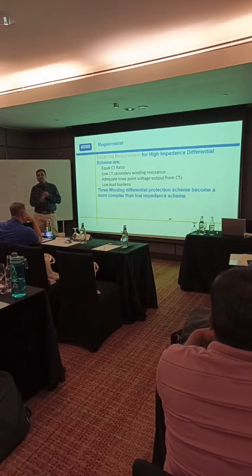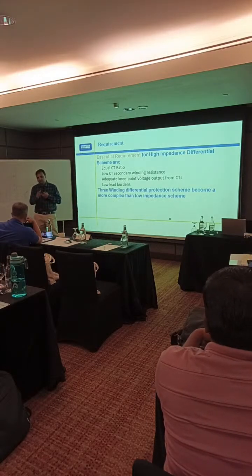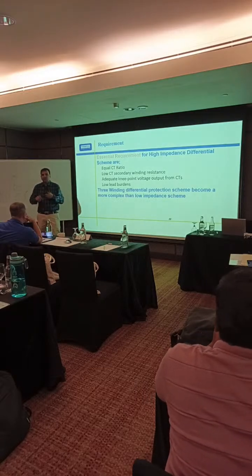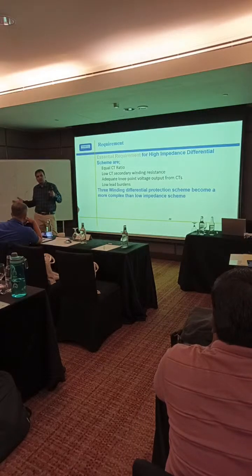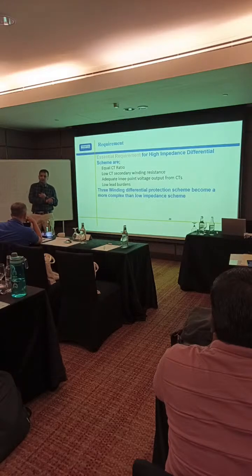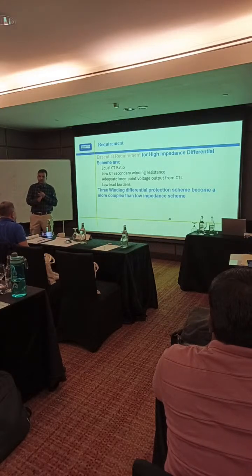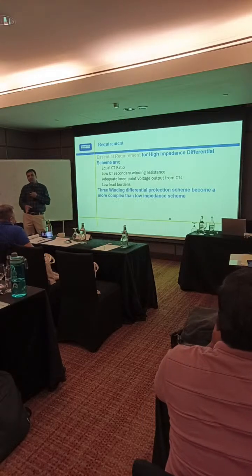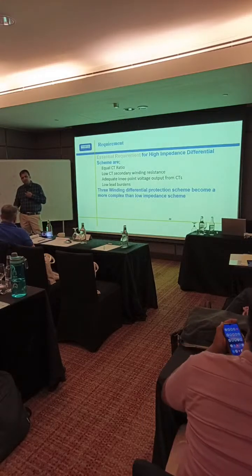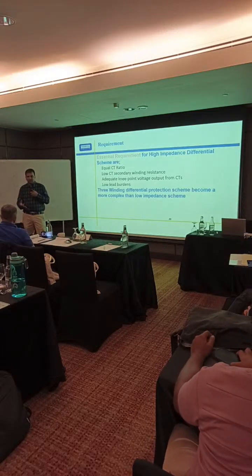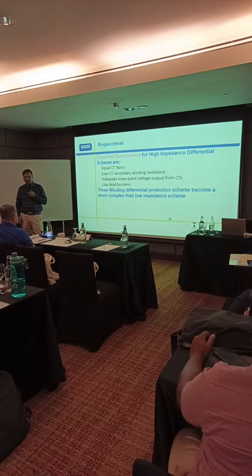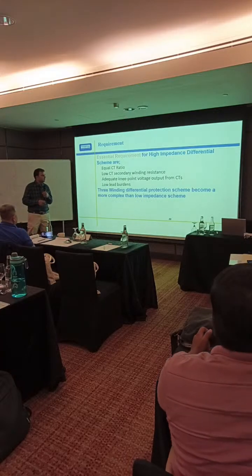Whatever relay we are using, if we want to find this answer, there is no standard answer. I cannot tell you one answer that will be applicable to all. It depends on the relay manufacturer's recommendation, how they are detecting, and they will advise the CT requirement according to that relay requirement. In any manual you open, I think in the first or second chapter, all the detail is there. This is not a standard.